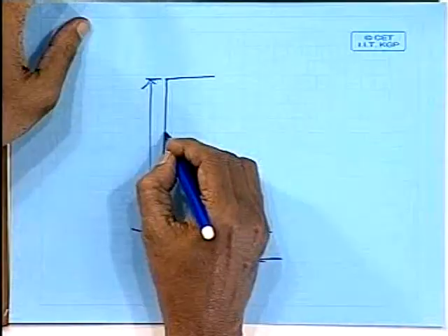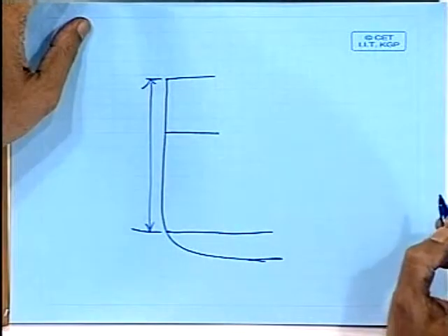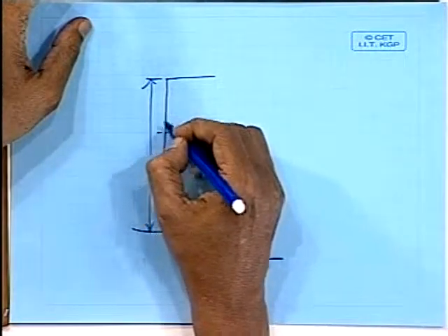The transverse frame will become very big in cross section, therefore very heavy. On the other hand, if I can break this span, then the scantling will come down. Typically in a twin deck ship, if I do two decks now, the span reduces to this and this, right?